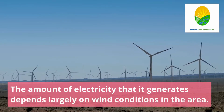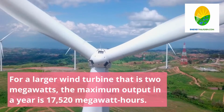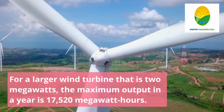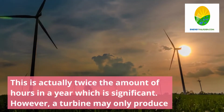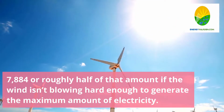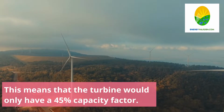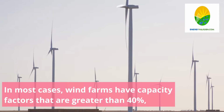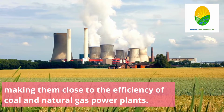The amount of electricity that it generates depends largely on wind conditions in the area. For a larger wind turbine that is 2 megawatts, the maximum output in a year is 17,520 megawatt hours. This is actually twice the amount of hours in a year, which is significant. However, a turbine may only produce 7,884, or roughly half of that amount, if the wind isn't blowing hard enough to generate the maximum amount of electricity. This means that the turbine would only have a 45% capacity factor. In most cases, wind farms have capacity factors that are greater than 40%, making them close to the efficiency of coal and natural gas power plants.